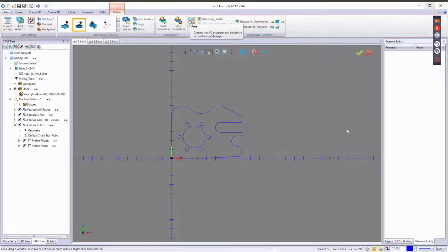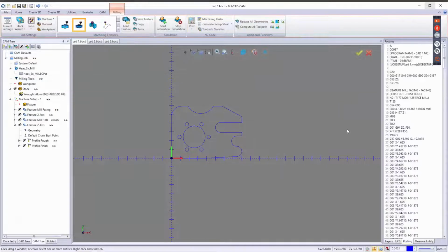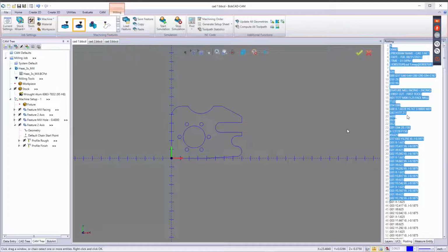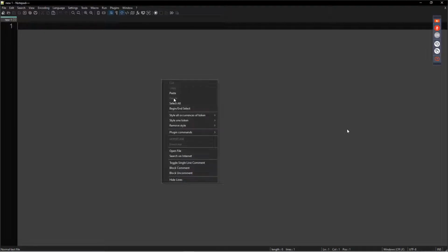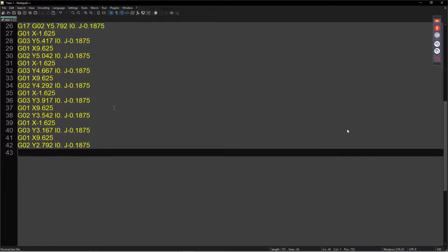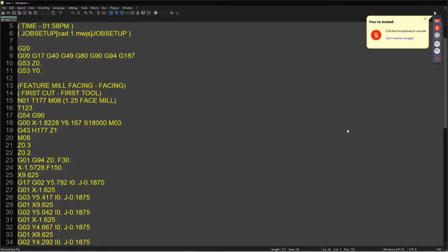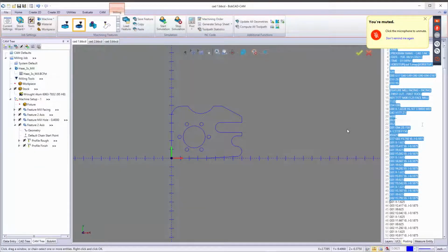And then from there, we'll go ahead and hit the little control box up here, the post our G code, and there it all is. Now I'm going to go ahead and right click. You got a few different options in there. Mach 3 and Predator, you'll see them, but you won't have access to them. Copy, what that is I can take this code and I can window select over the whole thing here. Right click and copy it, and then open up a Notepad, WordPad, or Notepad++ on here. Oop, let me say no, and I can paste the G code right there on that. So I got that. I can bring it into a Notepad if I need to on there.